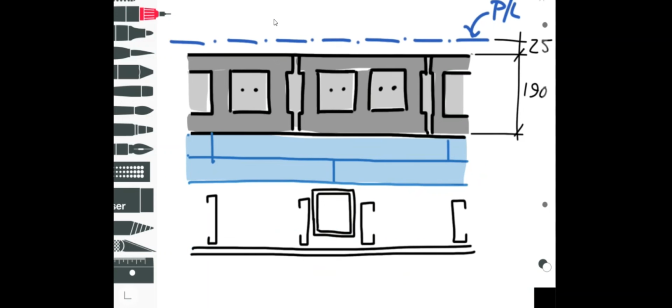And so maybe a better approach would be to do it this way and, depending on what your energy code requirements are, put in 2 or 3 layers of a rigid insulation, so an XPS type insulation. I say do multiple layers because you're going to have joints between the boards and you can stagger the joints. This thickness of XPS insulation is going to essentially work as a vapor barrier. So all you'd really need to do is tape up all the joints, and essentially you've got yourself a vapor barrier right there. So you're not going to have to worry about any condensation happening right there.